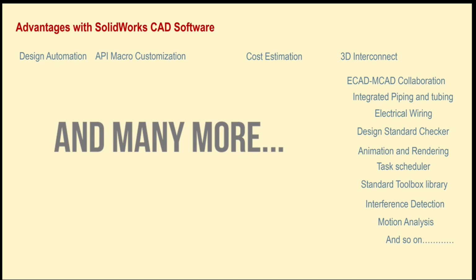So task scheduler can schedule your tasks similar to Windows task scheduler. It will schedule tasks related to SolidWorks, like conversion of files. Like if you want to convert STL files into SolidWorks files, designers use so many STL files. So instead of again opening each in SolidWorks part and saving it as a SolidWorks part, task scheduler will lessen the time and convert thousands of parts in just seconds.